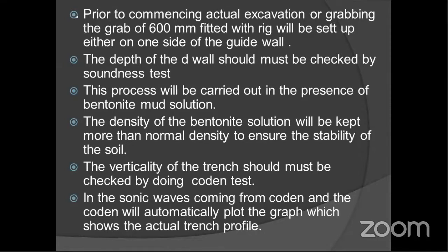So throughout the process, the one thing that should be maintained is bentonite circulation. That should be done regularly without any interruption, so that we can resist the maximum number of collapses. That will be beneficial for us, because once it collapses, it will be a rework for us to start at this site.